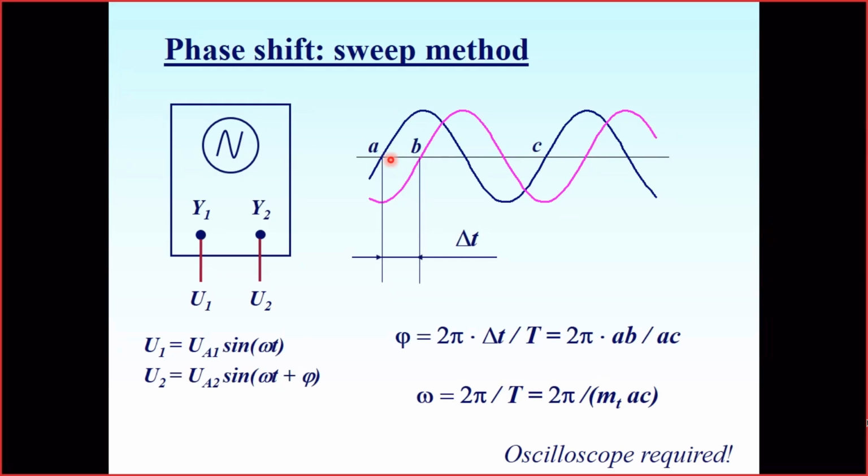For my picture, if we interpret the blue signal as the first one and the violet as the second one, then for this equation to be correct, we have to admit that phi is negative. The first signal is already moving, so the time has already progressed, but the second one, because of the negative phase shift, still has sine equal to 0 here.